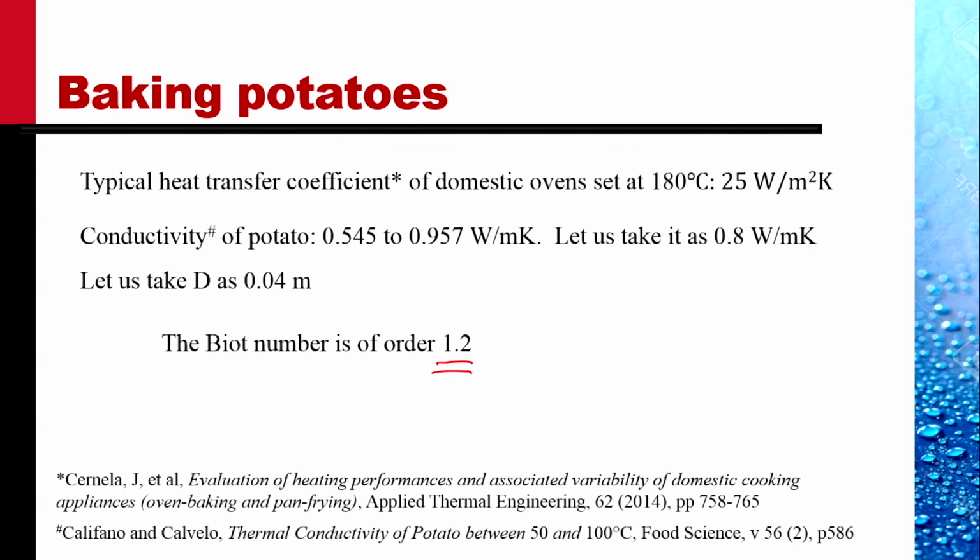And so the Biot number would be important. We could neither make the assumption that the Biot number is very small and assume the temperature throughout the potato will be constant, nor can we assume that the temperature variations within the potato are negligible and transfer the temperature Tf to the surface of the potato. So we'll have to use the Heisler charts. We'll continue with the discussion on approximations in the next lecture as well. Thank you.